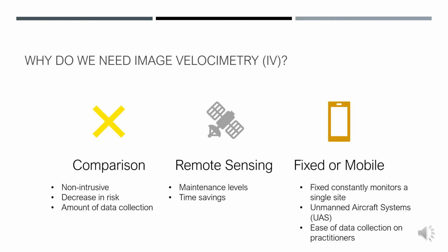So why is this method so important? Typically, when we want to monitor things such as rivers and discharge rates, we would have to implement something like a pressure gauge, or something that sits in the water and measures it intrusively. That can cause problems long term, with high flows causing damage or debris and weeds interfering with the apparatus. Other methods such as ADCPs also rely on touching the water, and that can cause a real risk to both the equipment and the operator, especially in high flows.